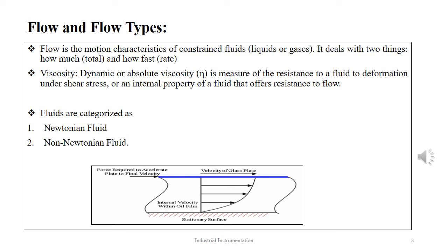Fluids can generally be divided into two types, Newtonian fluids and non-Newtonian fluids. When held at a constant temperature, the viscosity of a Newtonian fluid will not change regardless of the size of the shear force. When held at a constant temperature, the viscosity of a non-Newtonian fluid will change with relation to the size of the shear force, or will change over time under a constant shear force. Given here is the figure that depicts the Newtonian flow and the non-Newtonian flow.